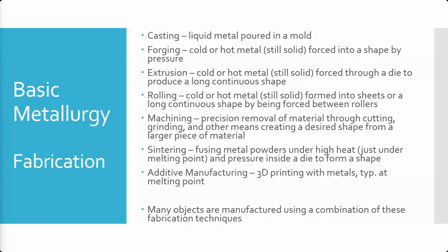So they can make a die and forge or extrude or cast parts, but with additive manufacturing, you don't have to have a die because you essentially have a print head. And so if you have low volume parts, aviation is one of the first places that you're probably going to see more and more 3D printed parts, because it makes sense to do that rather than having to make an expensive die. The die is the thing that the steel or metal gets formed in. Aluminum, titanium, they can all be formed by dies.